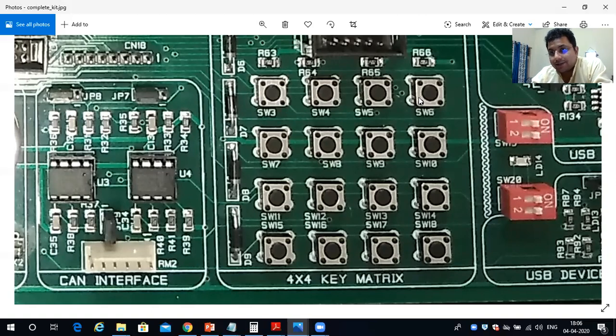Now it depends on you, how you will approach the problem. These 4 pins, the row, can be connected to 1 pin. That row we will use as input. We'll capture it and see whether the value is 1 or not. And these 4 columns, we will attach to 4 different pins as output pins. Those output pins will keep on varying.